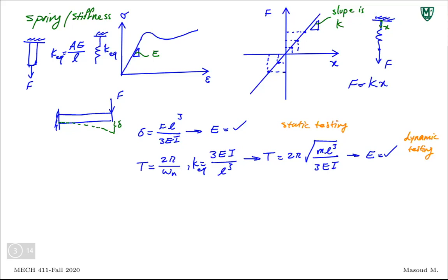So two parameters so far, I told you how you can measure. So how can you identify them for a given system? You're an engineer. They give you a system. They tell you, well, give me a model that behaves as close as possible to this real system under these specific conditions. That's what you're going to do probably in a lot of places you're going to work as a designer. That's actually an art, to be able to develop models that behave very close to the real system. So to do that, you have to get input from your real systems. How to do that? Well, mass and inertia, I told you how to do that. Spring is stiffness, depending on if you just have a spring or you have a solid system, you want to identify its parameters. That's what you do.